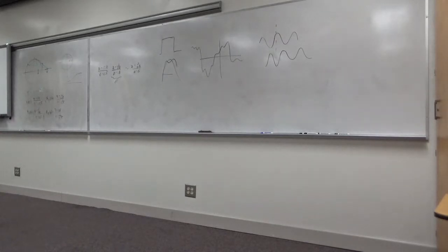Either one of those, back here, these two. 0 at 0.8, 0 at 1.25. They will have the same gain response. Why? Because to get from one to the other, all I have to do is multiply by an all-pass filter, which doesn't affect the gain response.